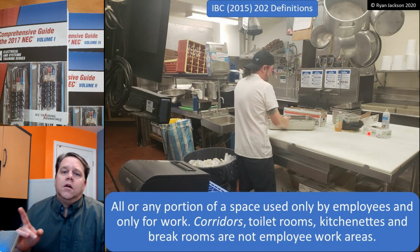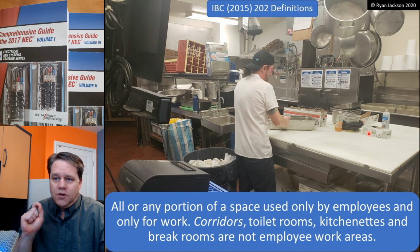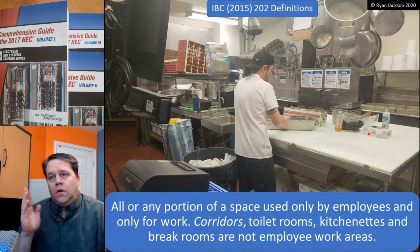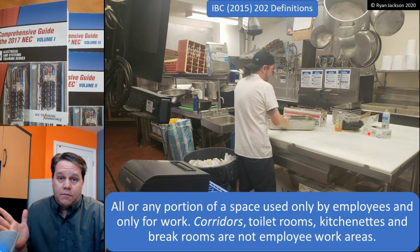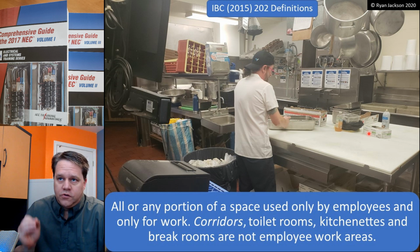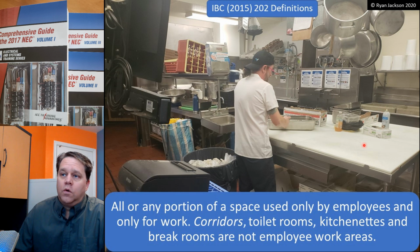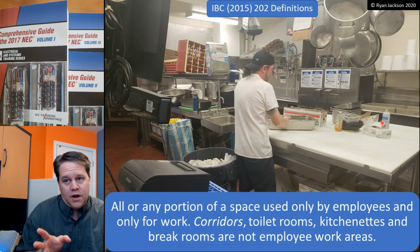Now, an employee work area, though, is defined, and that's all or any portion of a space used only by employees and only for work. So here we have a commercial kitchen that would only be used by employees and only for work. I'm not going to do anything else in that commercial kitchen besides employee work. So that would be an employee work area. What's the height of this work surface? How deep is the sink? Can I get a wheelchair under the sink? None of these things would apply because that's an employee work area.